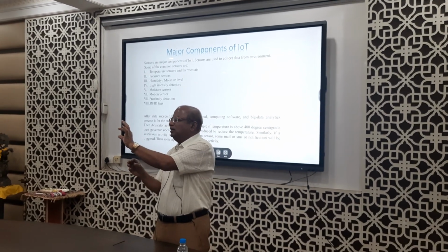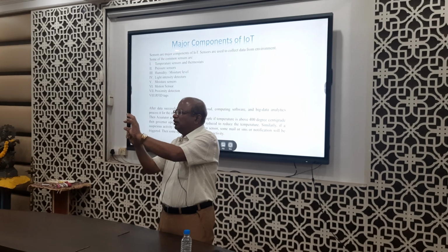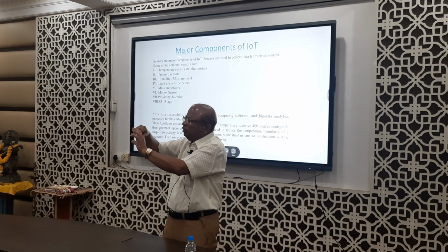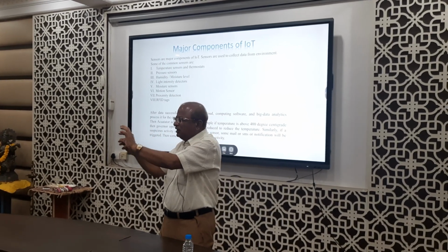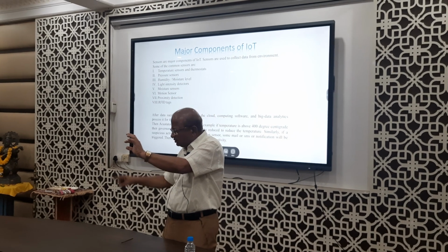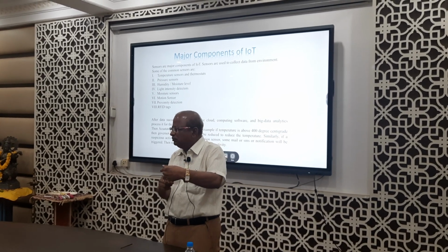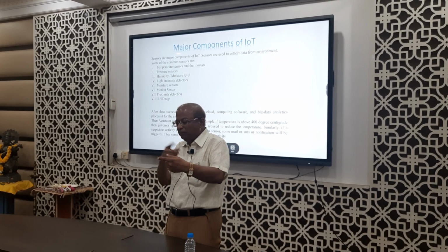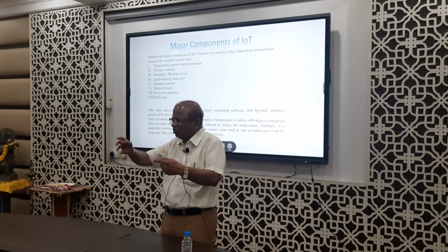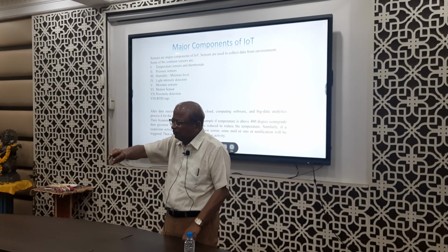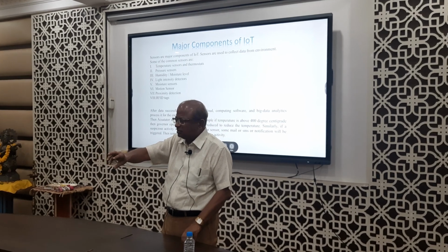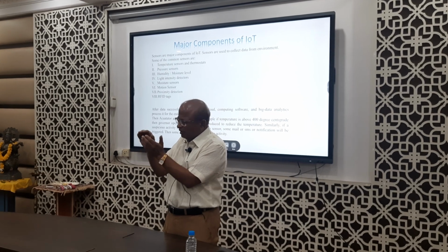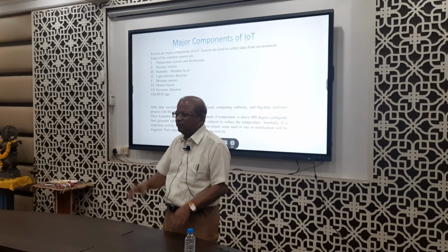Then again I am giving you one example, a very easy example from my side. For example, corresponding to 400 degrees centigrade, 8 volt. Suppose it becomes 420, it becomes 9 volt. If it is 410, it is 7 volt. That signal is fed back and compared with one standard signal. The difference is 1 volt or 2 volt, plus or minus. Accordingly some governor opening, just like we open or close a tap, will be opened or closed in the appropriate direction, and accordingly the supply of steam, water, whatever, will be reduced or increased, and then the temperature will be maintained.